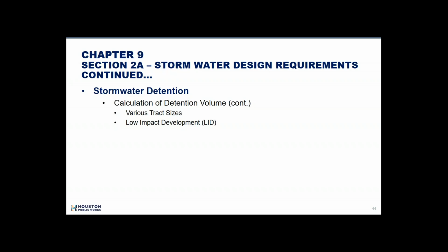If you use low impact development or green infrastructure, that's going to kick you into the stormwater quality side, where you'll need to provide us with some sort of a permit. We'll ask that it be permitted so that we can verify that it's there year after year after year, versus some sort of open system that is storing water.